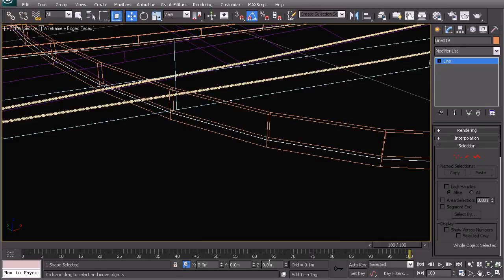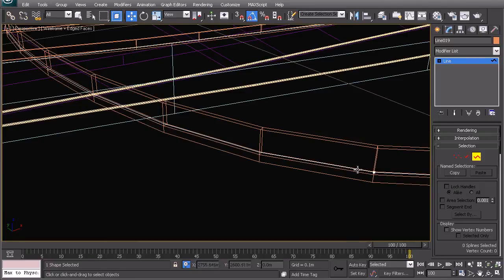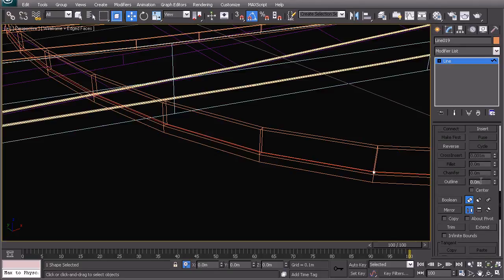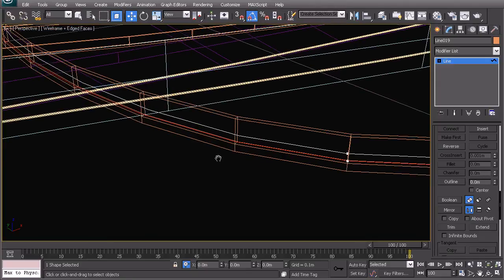So we want to move it slightly higher so that it doesn't interfere with our slab. So we can just move it up by, let's say, 0.1, and we can just bring it in slightly smaller. So let's select the edge, and going across to outline, let's just go minus 0.5. And now that's brought it in slightly. So let's just hit delete, and that'll delete the outer edge.